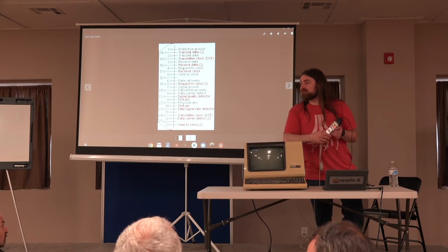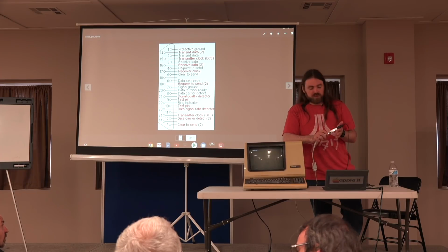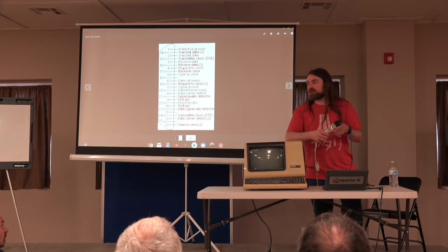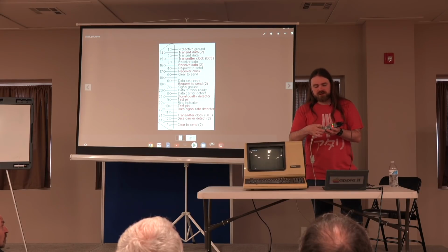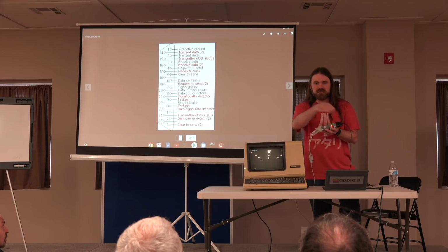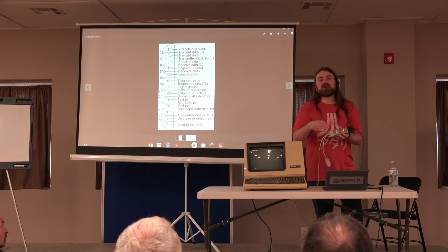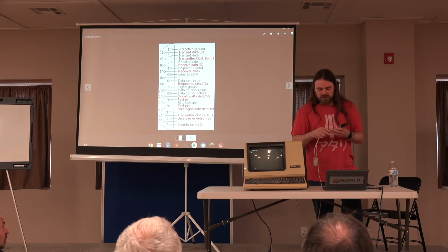Another question? I'd also recommend if you're doing that, a breakout box. The breakout box is definitely helpful. I have one. I didn't need it for this setup, but a breakout box would just take the 25-pin connector, break it out to pins that you can easily connect with jumper wires, so you can see what's going on. Very handy device to have.